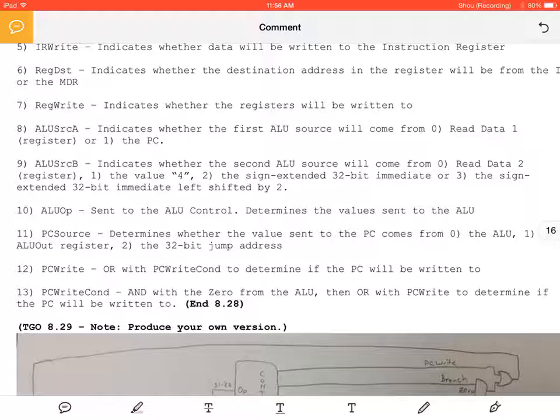That's the third one. Structural hazard. There you go. I knew it's in your brain. I promise it's there. So structural hazard is what happens if 2 things are trying to access the same thing at once, right? So if I combine instruction memory and data memory into one memory, I have an instance where I'm trying to get instruction or get data at the same time, potentially. And we use that I or D control signal to eliminate that hazard.